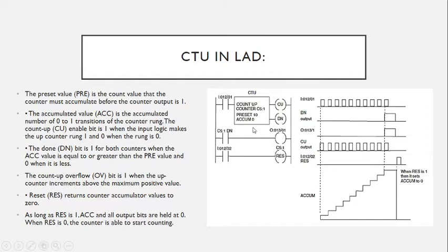The done pin is used as the address for activating another contact here, and that contact is connected to another output. And then we have another input for the reset, and you can see that the reset is connected to our counter. So looking at the time plot, we can see how exactly the counter is accumulating.